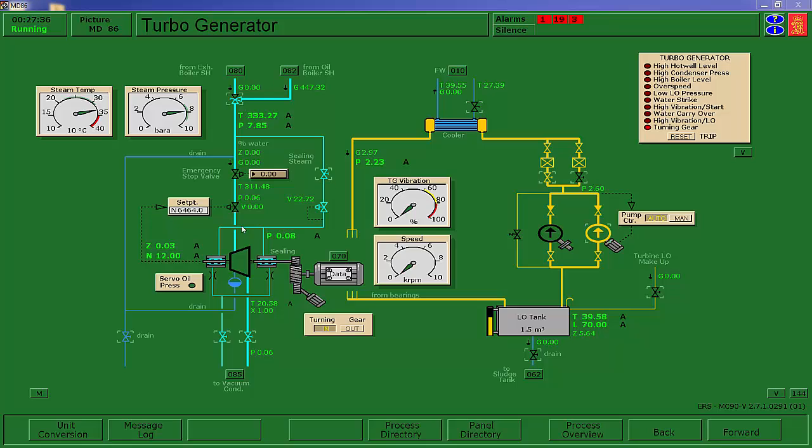I had to put gland sealing steam on to raise vacuum. The gland sealing steam tends to warm the shaft of that turbine on either side, preventing the leakage of air into the condenser. But also, whenever you're warming up, getting a turbine ready for operation like this, you always have the turning gear revolving the turbine prior to actually startup. Otherwise, you take a chance that the turbine rotor can sag and cause vibrations on startup.